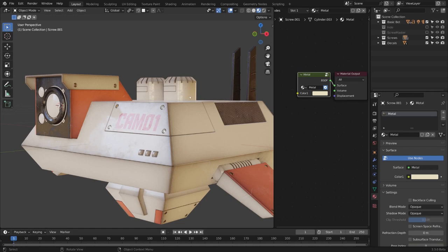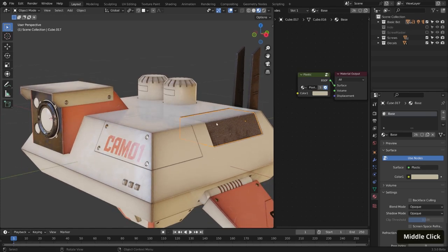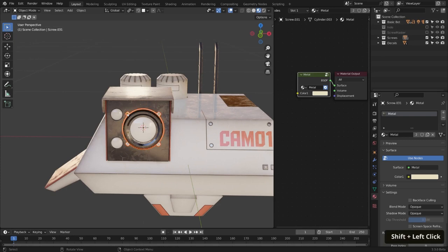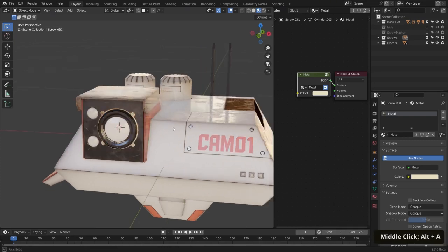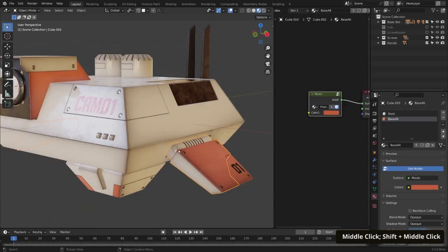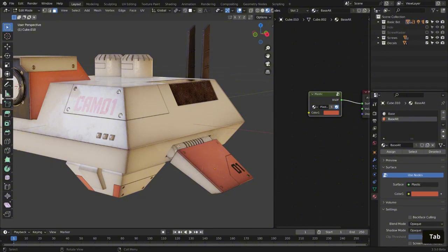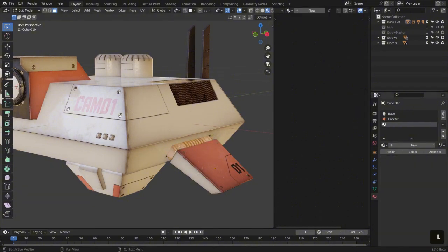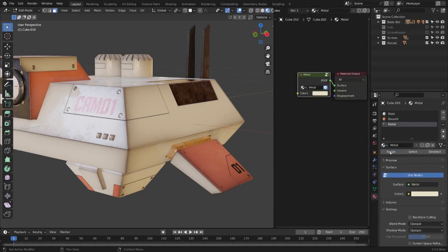And there are a few other areas that I feel should be metallic. The fins, definitely. So let's click those. Click our screws and link materials. This bracket here, click that and a screw, link materials, the join under our wing. Let's jump in, select the join, create a new material slot, and just select metal from the drop down and assign.